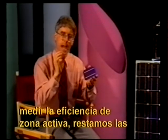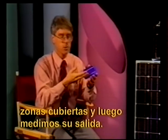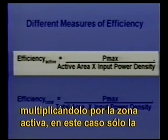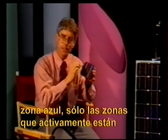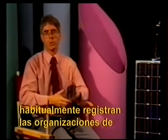So if we want to measure the active area efficiency, we subtract away any areas that are being covered up to make an actual cell, and then we measure its output. The efficiency is calculated by measuring the output of a device and dividing that by the density of light that's shining, and multiplying that times the active area only, in this case, the blue area, only the areas that are actively producing output. This measure of active area efficiency is what's typically quoted by research organizations.